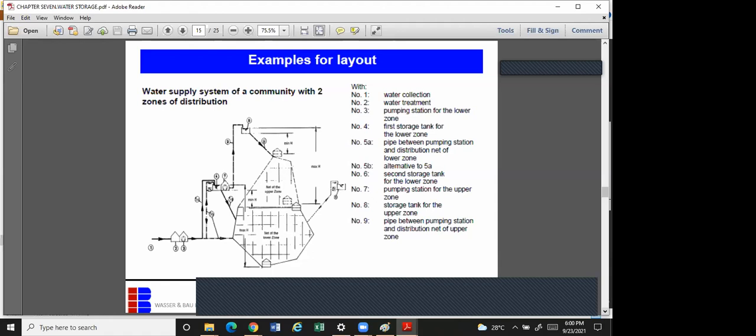It happens in most of our universities, because when they designed this thing, they didn't factor in the service pressure. As you are going up, you're increasing it. But if you use 20 to design everybody, and you now go and build a 60-story building, the service pressure should be 20 plus 5 plus 5 plus 5 plus 5, which is about 50. So service pressure for a 60-story building should be 50 meters of water, or 5 bars. So if you use 2 bars to do it, that means when you get to the 4th or 5th floor, water will cease, especially during the peak period, thereby making the person uppermost not to see water.